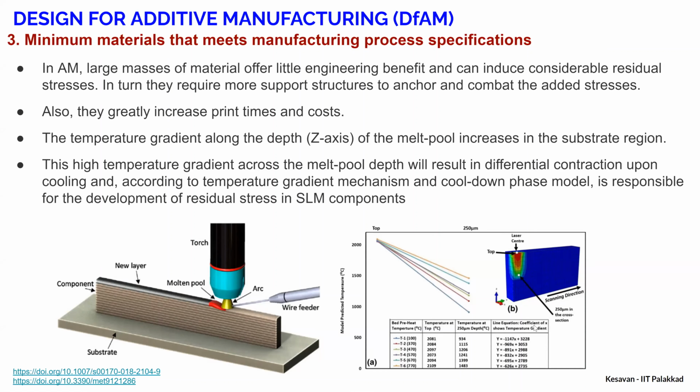Higher heat input is generally not suggested for structures, particularly if you are making a component for a structural application wherein it has to withstand either static or dynamic loading.